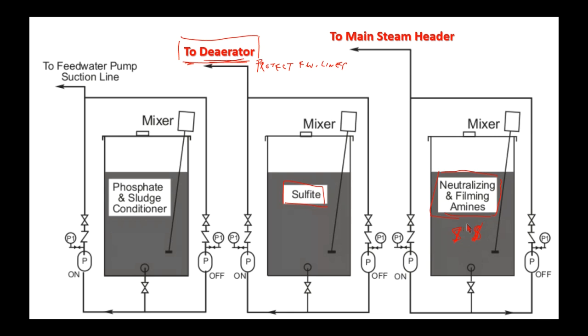So if we feed that into the boiler, every time we operate the continuous blowdown, and every time we do a bottom blow off, we blow these chemicals into the blow-off tank and down into the sewer, and what a waste of money. And what a waste of chemical. So where plants are normally injecting this stuff is into the main steam header.